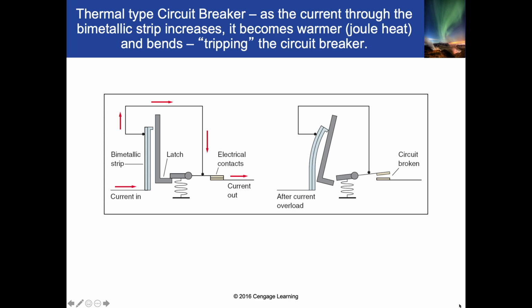And so what do you do then when you want to restore power to that part of the house? Well, first thing, have you ever tried to reset your circuit breaker and it doesn't work? It doesn't actually return power to the house, and you're like, what the heck's happening? The reason is that this is probably still bent, and you need to let it cool down first. So that's the first thing. Then after a while, you do it and it works fine.